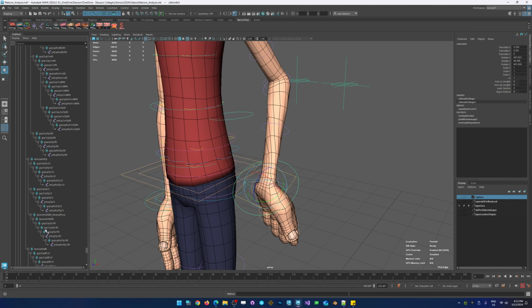So if you look carefully, you're going to notice that each object in this rig has so many parent nodes. The reason is that some of these are for helping you with gimbal locks. Some of them are for zeroing out values. Now here's the thing. Autodesk did make an update recently where it now has the parent offset matrix. So zeroing out objects has never been easier. You can now zero out position and rotation on any object, and that's not something we had before. Before, we had to create extra objects to zero out their translation if it was a joint.